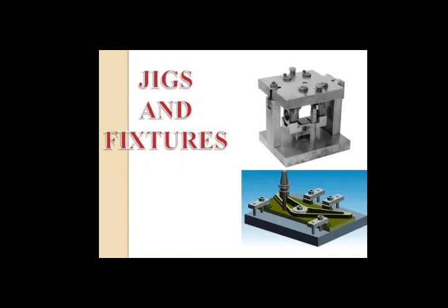Dear friends, while studying metrology and quality engineering, you will come to know that inspection devices are an integral part of the manufacturing industry. For example, a go-no-go gauge is a simple gauge that can provide you an inspection fixture for 2 times. That is, it will check the go dimension, the possible allowable dimension. Again, at the same gauge, you will come to know that the no-go gauge will perform the operation for not allowing dimensions.